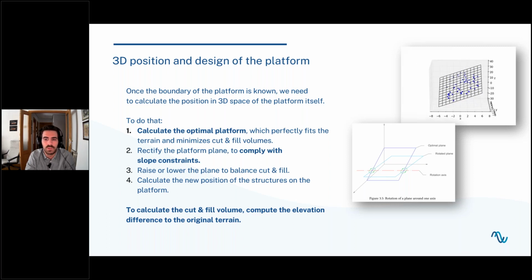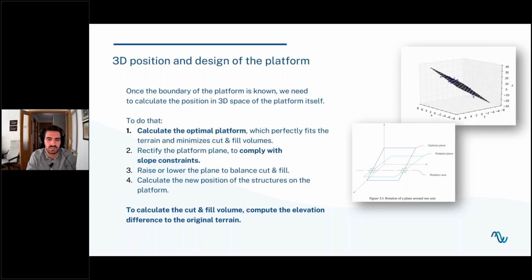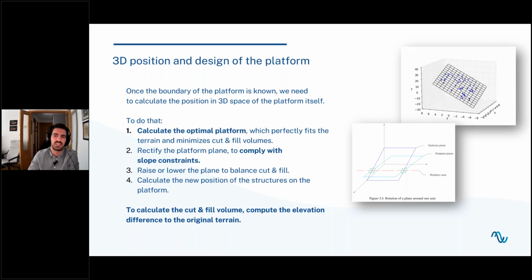Then we move the plane up and down so we can balance cut and fill. Right now, pvDesign will find a perfect balance, a 50% cut, 50% fill balance. And finally, we reinstall the structures on that plane, and that gives us the final result.